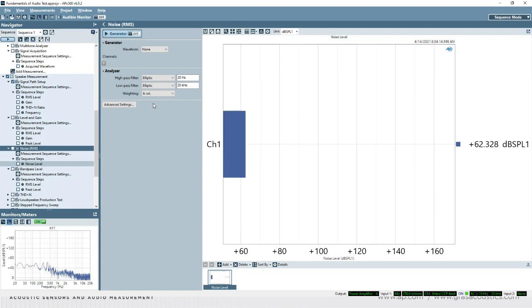However, real world audio devices have various nonlinear and time variant effects. Particularly when we talk about speakers, speakers heat up as you play a signal through them and their behavior changes. One observation is the crest factor of a pure sine wave is so much lower than that of typical music that it will heat up a speaker much more.